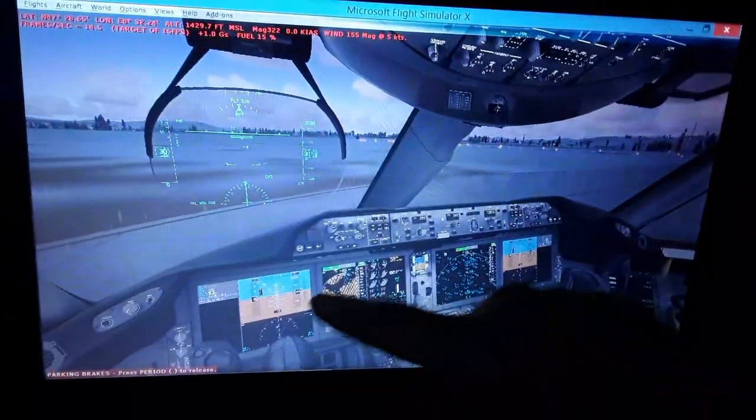The flight management computer is going to calculate automatically the center of gravity of the aircraft for takeoff, climb, cruise, and approach and landing with burned fuel. So the center of gravity is shifted and it's recalculated every second in flight by the flight management computer. Also for takeoff, we have the mean aerodynamic chord position, 23%, the maximum aerodynamic lift, and we can also see the stall speed. Using the center of gravity, it also calculates the horizontal trim stabilizer position for takeoff, 4.35 degrees. It's going to be set automatically by the flight management computer.